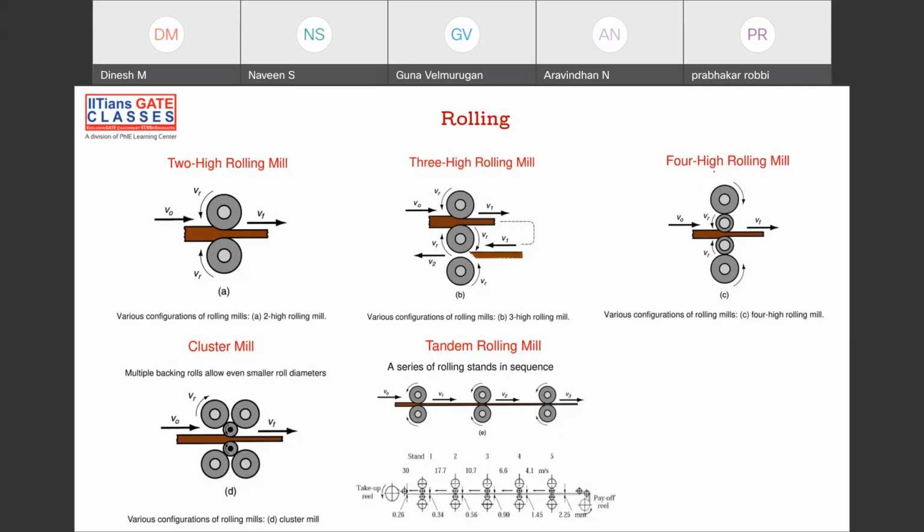this is for the high roll mill, because you want large reduction. Why are we doing these two things in the first case? Because a sudden large reduction is not possible, because rollers are mounted on bearings. If you send in a large reduction, the bearings have some forces, and they have to stay intact. Otherwise there'll be a failure of the bearings, and if bearings fail, the rollers will come out. You can't do that, right?